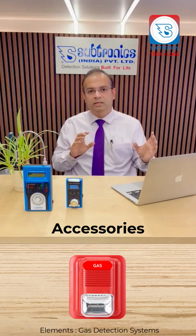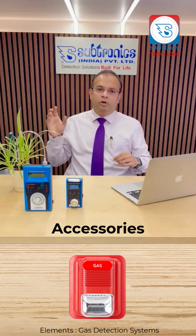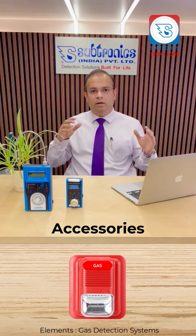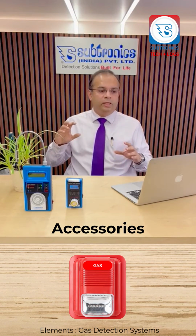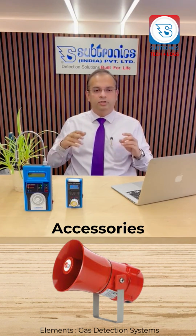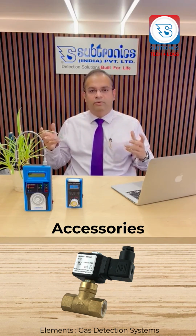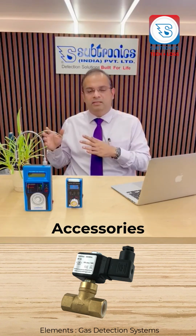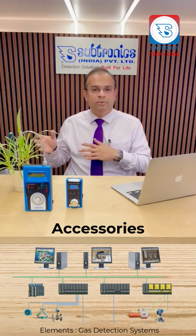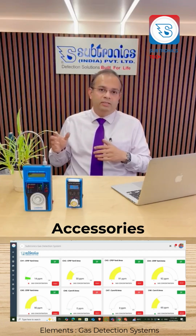And the third element is the accessories. Accessories can be anything like a small siren in case of gas leaks; above a particular level, you get the siren. Or it can be a hooter, or an exhaust fan switching on automatically, or a solenoid valve which is going to shut off your gas supply. It may also be connected to a DCS, a PLC or a SCADA, or even nowadays an IoT system.